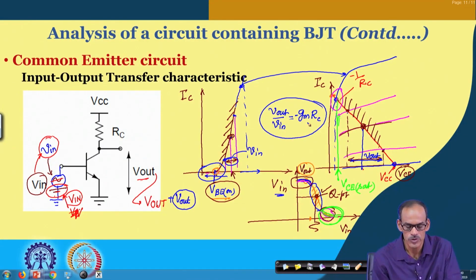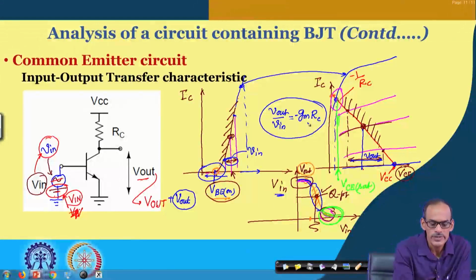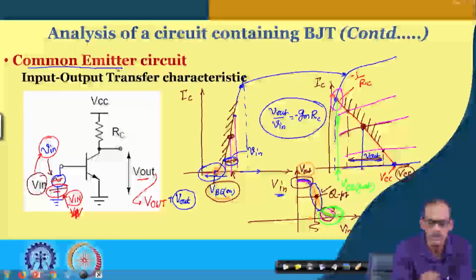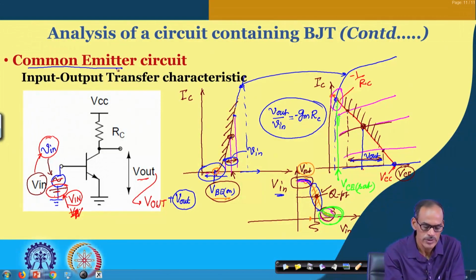And as I said, we do have a notion called amplification. This circuit is providing a good gain, and we call this circuit a common emitter amplifier. That is because the signal we are applying here is at the base, and we are observing the output at the collector, and the emitter is connected to either a DC voltage or, in this case, ground.